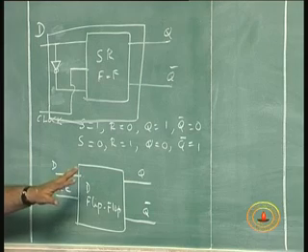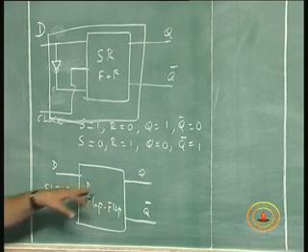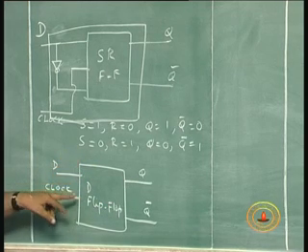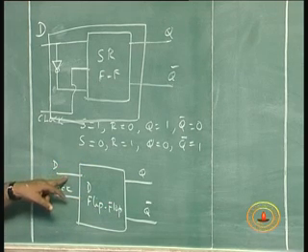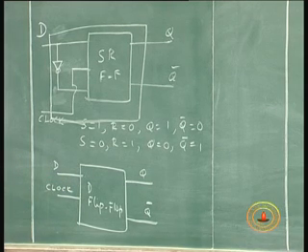If you want to read it, you can always read it any time, because even without the clock the Q remains 1. But if you want to change the data, I need to put the clock again, with the new value of the data. So, the D flip flop is a very simple 1 bit storage, which is most frequently used for data